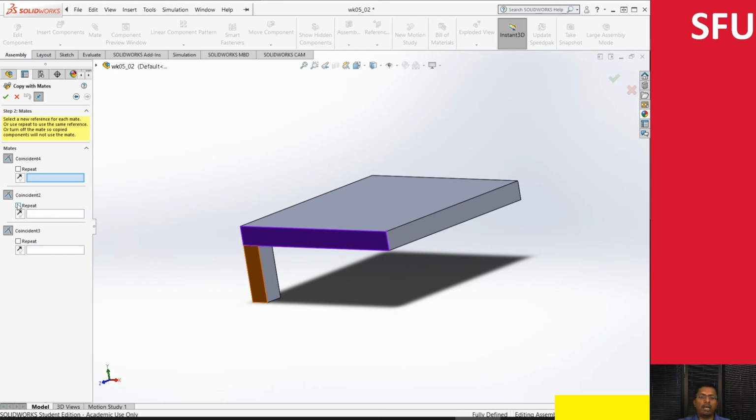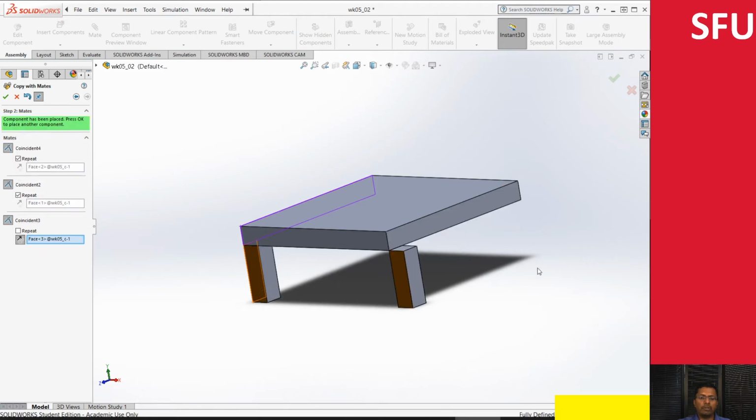So let's maybe make the top repeated. That means it's assembled, mated here and here. And I'll maybe repeat this mate as well, so my leg is at the same location. Now here, instead of mating with that face, what I can do is maybe flip directions and then select this face. So then it's put it there.